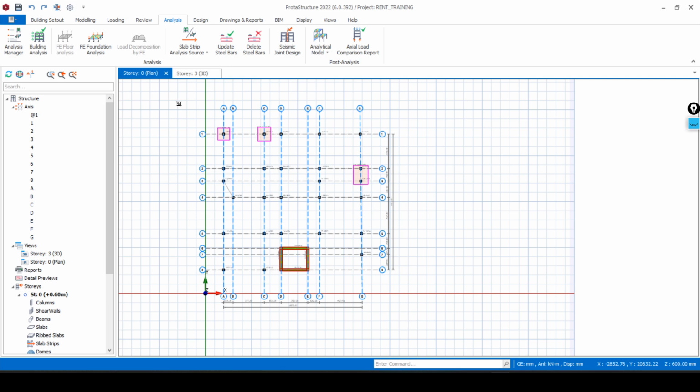So it simply means you now have to change to another, suitable foundation type. You can consider using the strip foundation or strap foundation, or you can go as high as using your raft foundation, depending on the bearing capacity of your soil. We also have the option to set the bearing capacity of our soil, the factor of safety, and the bearing capacity that will be required for different types of foundation design. Are you following? We are going to be covering all that in our advanced classes.